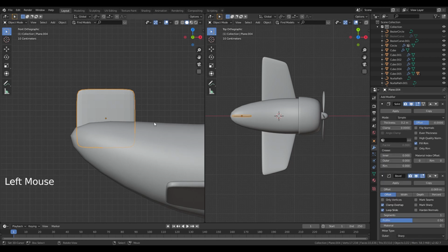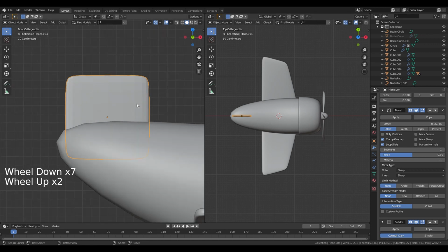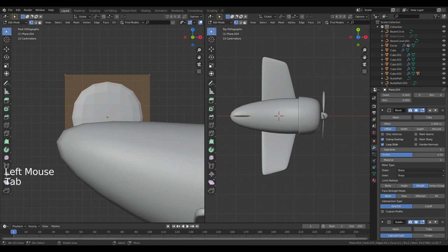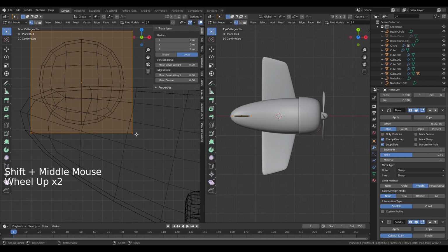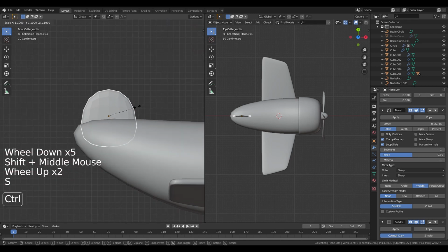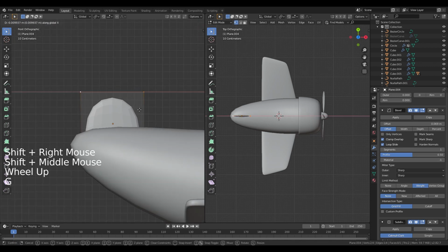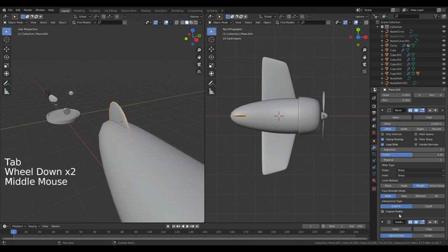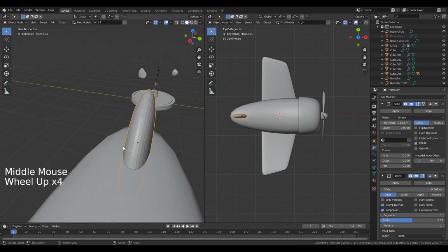And also we don't need the limit method to be none, but we need a weight. Set up the mean bevel weight. I'm going to go into wireframe, press N, so I have this transform menu over here, and I'm going to choose the bottom vertices and increase the mean bevel weight to 1. Back in my solid view, I can see what happened. Now I can just choose these vertices up here, move them on the x-axis if I want to make it sharper, and increase the subdivisions to 3, and I can also increase the thickness slightly, shade smooth, and that's it.